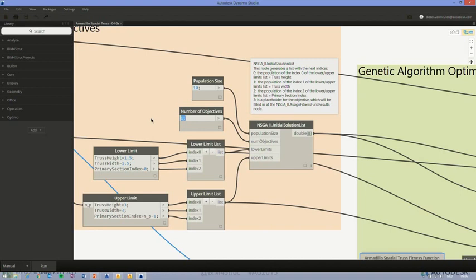Now, at the end, I will get this result, right? That Watch node tells me that the ideal truss height is 2.33, 1.71 for the truss width, a specific section type that is used, and I get that weight score of 11,000, which is good for me. I'm happy with that 11,000. And with that parametric run I did, you can check if that result is also somewhere in there and find some more information about how many members have been overstressed. None, of course, because otherwise it wouldn't be an optimal solution. But you can look for the ones that are over-designed, and maybe you can track it afterwards in that Excel list.